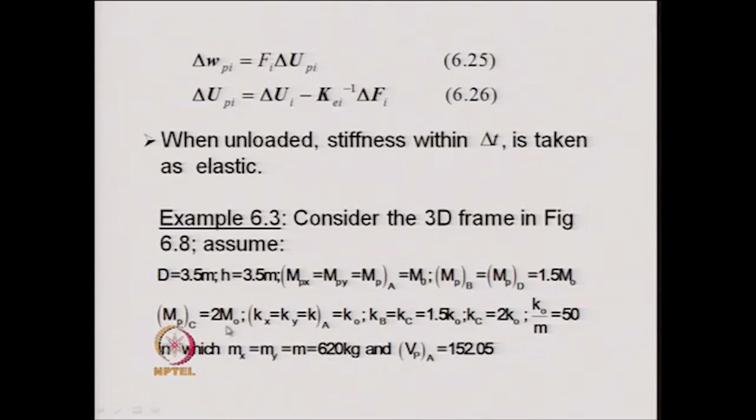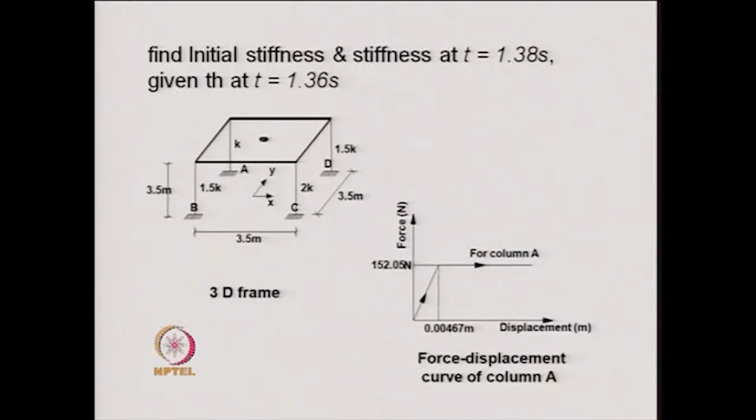So, since the moments are in this proportion, the yield shears also can be obtained in that particular proportion. So, we know the yield shear for all the columns.